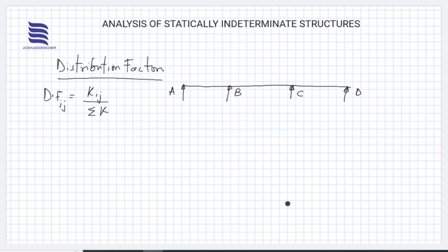Right. So if we have stiffness for BA to be 3EI over L, and your answer obtained was 0.22, then you have stiffness for BC to be 4EI over L. We should know the reason why it is like that. Then we have 0.24. I do not know, but these are educated guesses actually.